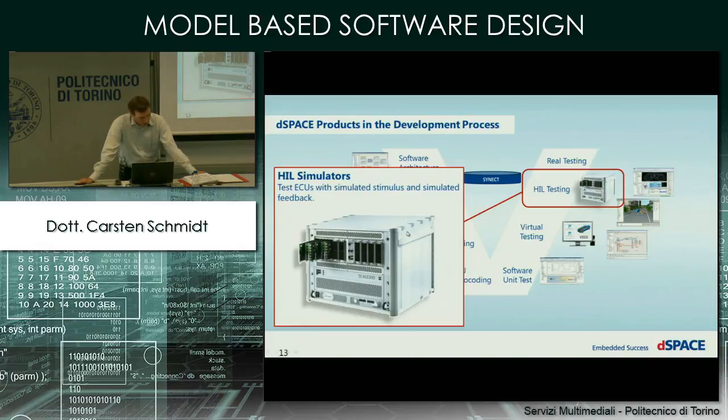And of course, you need some additional tools to be able to use such a HIL simulator to really test ECUs. So you need a kind of interface tool to, for example, define tests, to visualize tests, and so on. And these interface tools are shown here.